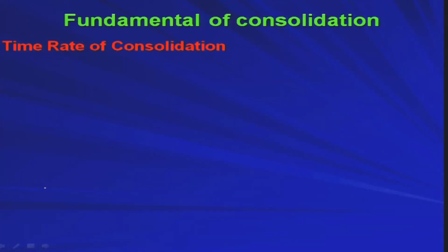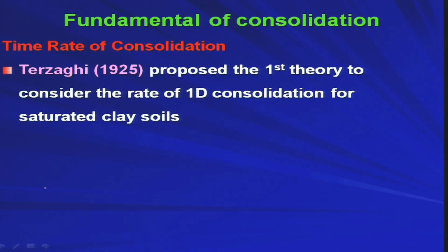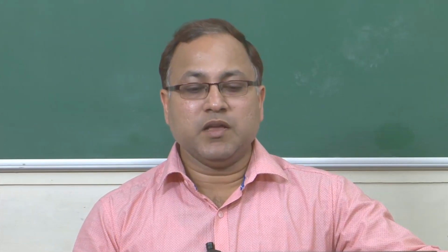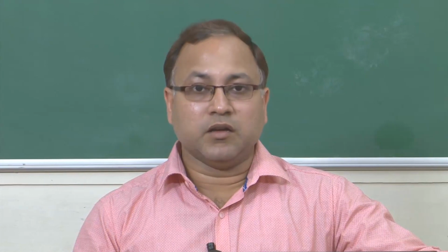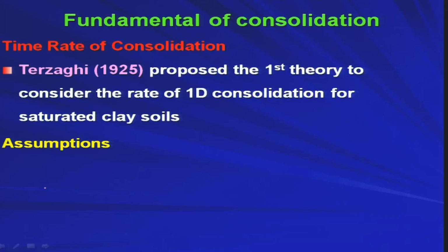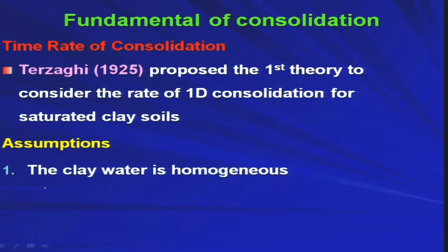Now, time rate of consolidation. Terzaghi in 1925 proposed the first theory to consider the rate of 1D consolidation for saturated clay soils. Now, we will try to develop the 1D consolidation theory. Based on that, we can calculate the consolidation for a particular deposit under completely saturated conditions. Now, what are the different assumptions?